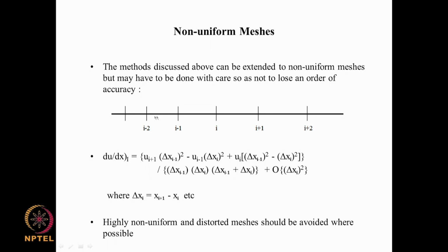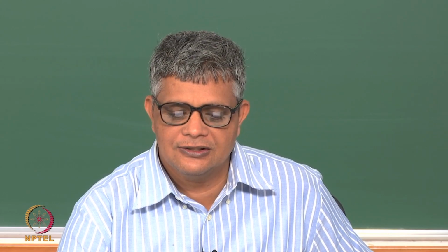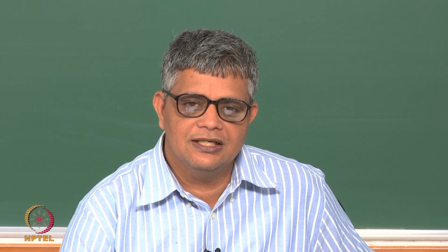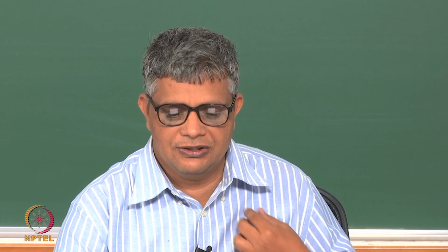Although it is shown to be gradually increasing, almost in proportion like a geometric progression, it is not necessary that it should increase in a specific way. But we do use this kind of geometric progression of the grid spacing, for example, in regions of large gradients like in boundary layers and so on. A grid with spacing which is changing is a non-uniform mesh.